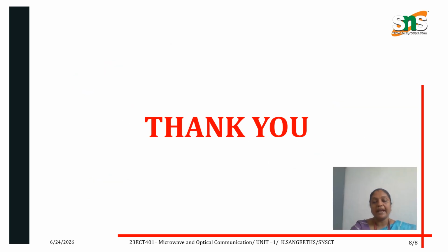So the main difference between the reflex klystron and the two cavity klystron is that the reflex klystron is a single cavity microwave oscillator that uses velocity modulation and a repeller electrode to generate microwaves. But the two cavity klystron is a microwave amplifier using buncher and catcher cavities to efficiently amplify high frequency microwave signals. I hope this video will help you understand what a reflex klystron and a two cavity reflex klystron are, and the difference between the two of them.